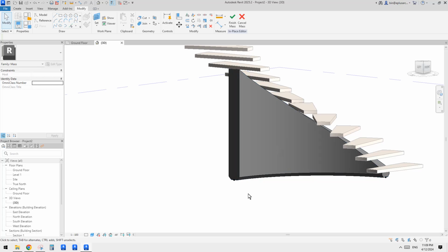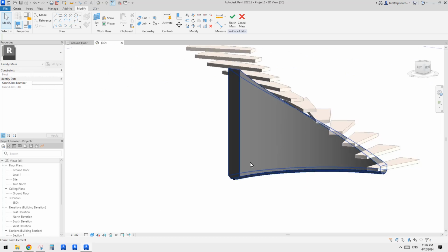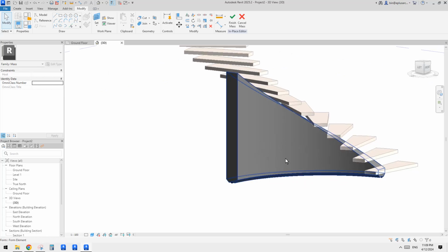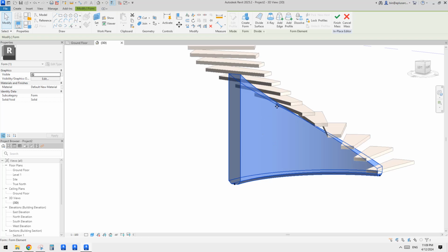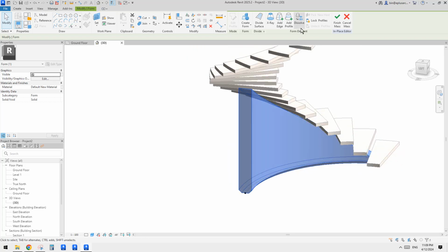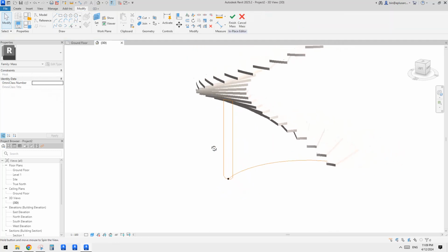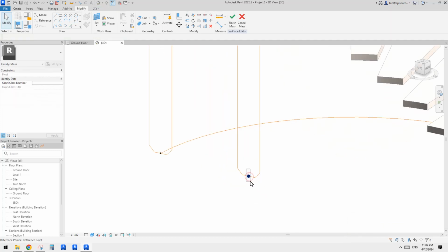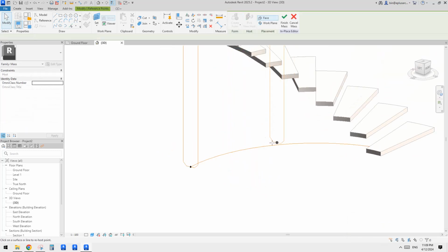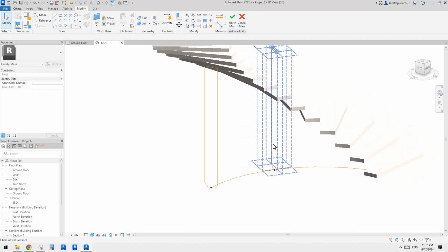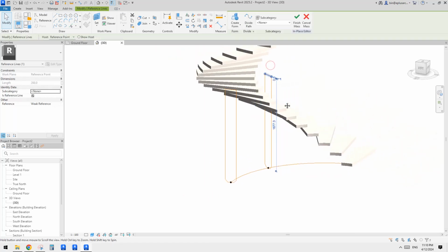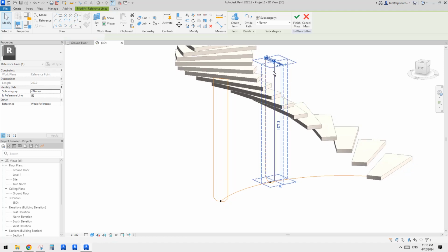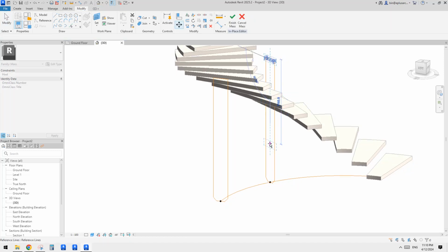And then so you can see we can't create that curved shape, so we have to add another profile. So let's just dissolve this one. I'll select this CC and select this point and pick new host, so roughly in the middle, right? So maybe here. And then we're going to select the top reference line and move it down, so maybe here.